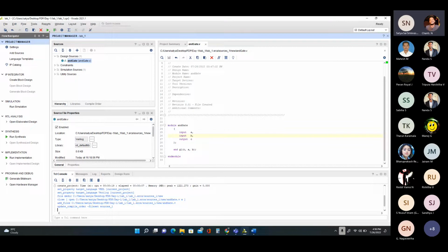After designing any hardware module, you have to do testing. Earlier I mentioned that to test a module, you also need to write a test bench in Verilog to verify its functionality. But since this is a simple module, writing a test bench is optional. That is not an issue. Even without a test bench we can do the simulation. I will show that today, and tomorrow we will see how to write customized test benches.